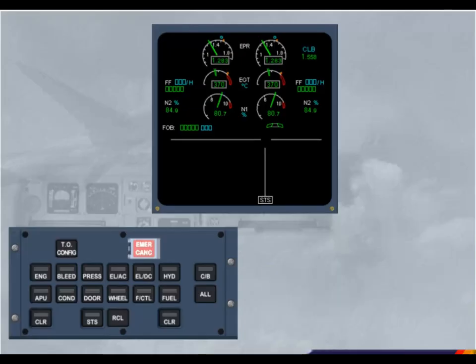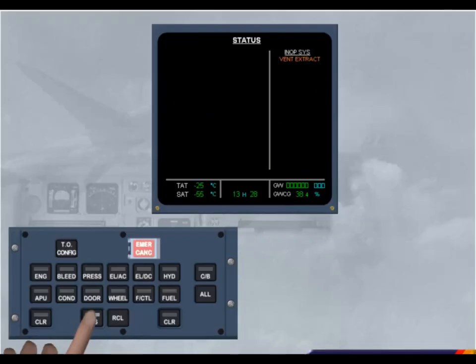During the approach phase, there is no automatic call of the status page when flaps 1 is selected or when QNH is set. To remind the pilot to review status, the box status symbol on the engine warning display pulses. The status page should be selected as before.